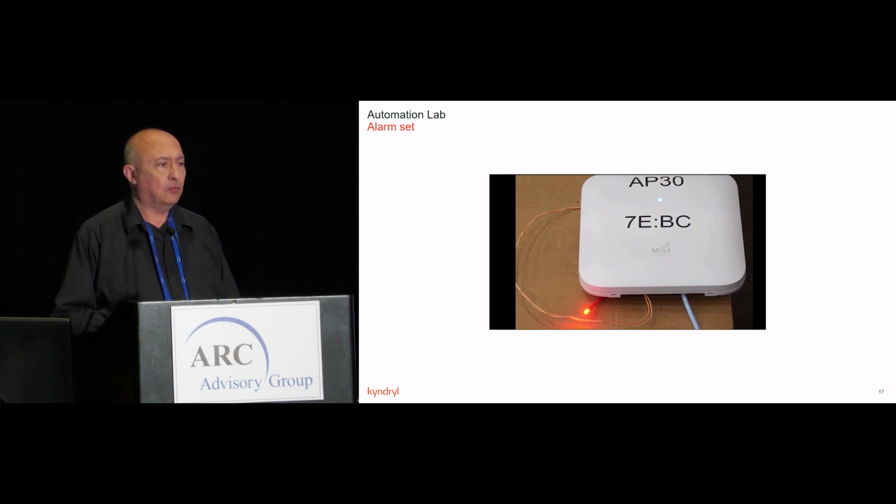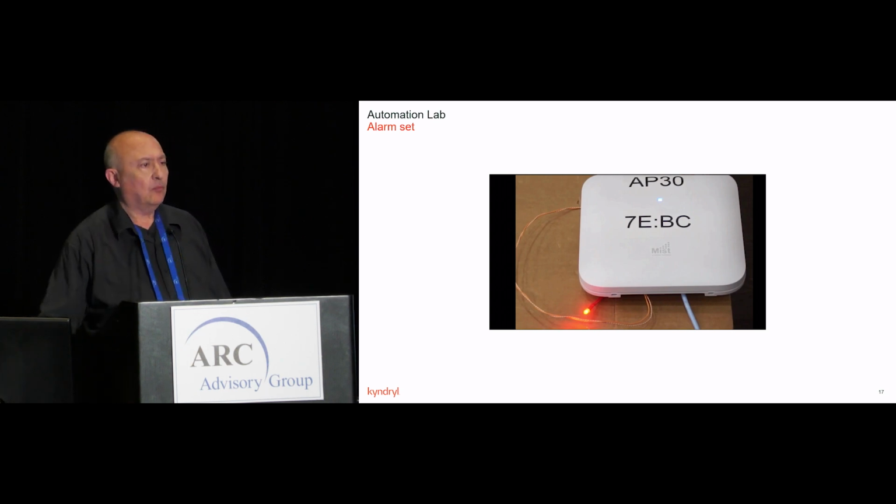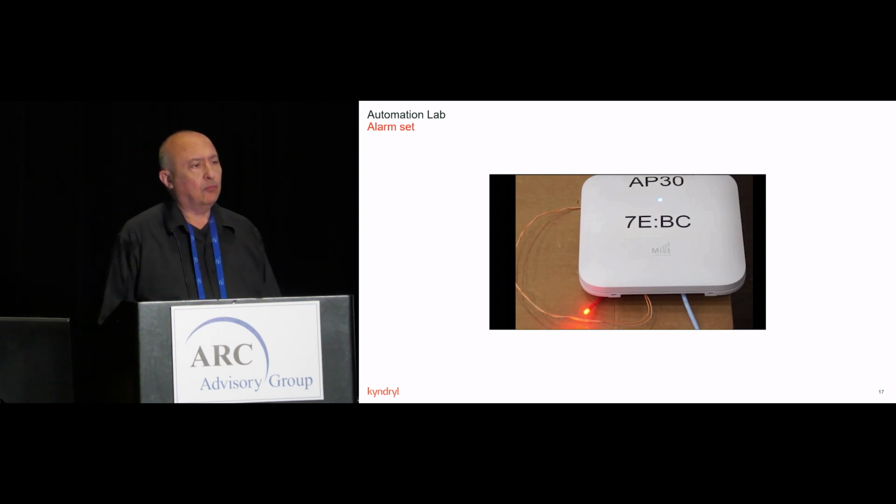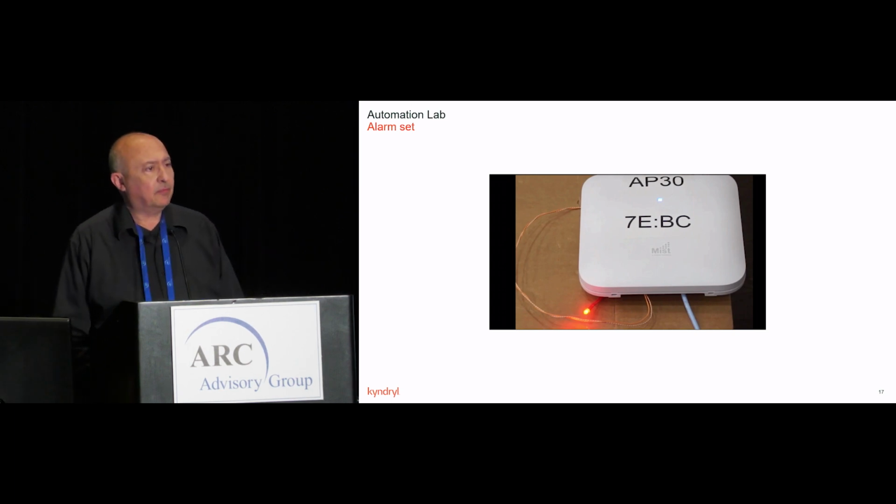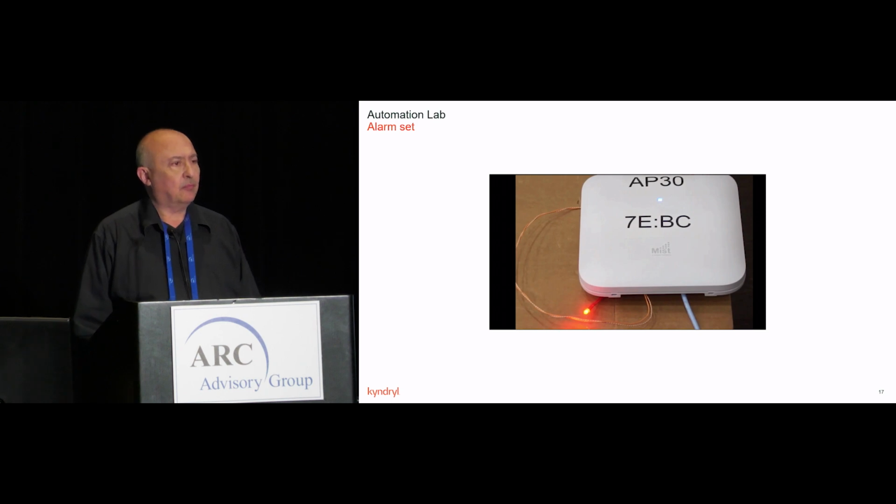Dominic, were you asking about hazardous area location? So there is hazardous area LoRaWAN equipment available. Yes. Because I've done it on offshore platforms and we've done it in hazardous facilities. LoRaWAN has some advantages and benefits and capabilities, really good especially around the idea of geolocation, locating assets without having to have GPS reception everywhere, on a multi-level offshore platform. There are a few providers that package LoRaWAN with hazardous area classification ratings.